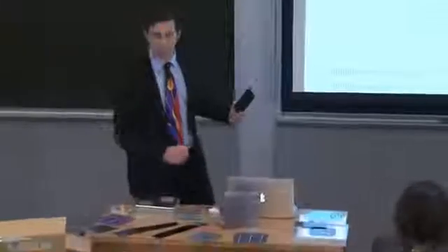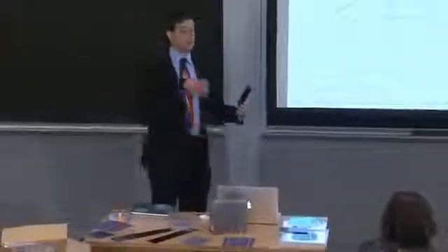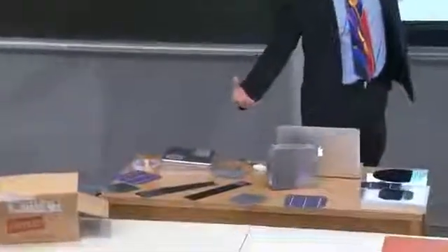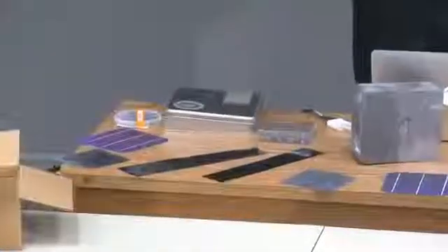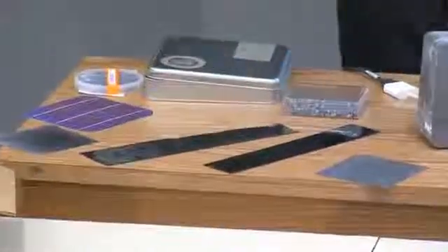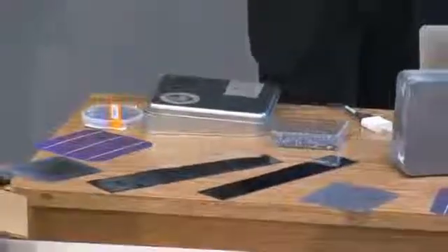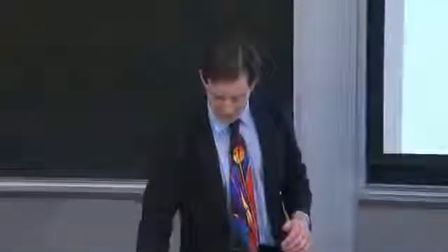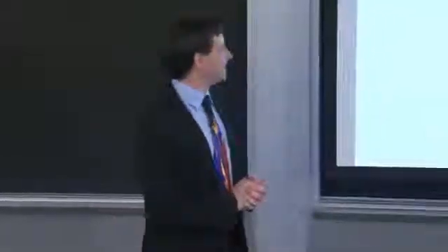As you can see, this larger ribbon right here, these can grow up to be a few meters long. They're rather long. You can pick them up if you have gloves on your hands. They're quite flexible at that length. You could actually even bend them with a radius of curvature of about a couple of meters. So the reason you wear gloves, obviously, is to prevent your fingers from soiling the wafer. We talked about sodium contamination and other forms of contamination. Silicon is non-toxic, so it won't affect you. It's really you affecting the wafer, much like putting fingerprints all over a nice, clean photograph.